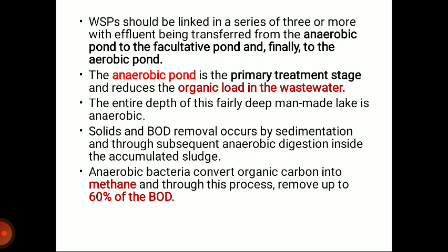The entire depth of this fairly deep man-made lake is anaerobic, and BOD removal occurs by sedimentation and through subsequent anaerobic digestion inside the accumulated sludge. Anaerobic bacteria convert organic carbon into methane, and through this process remove up to 60% of the BOD.